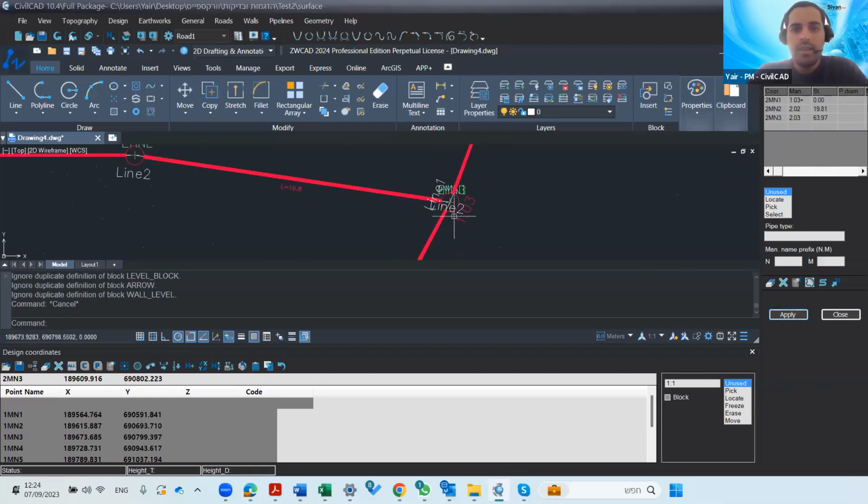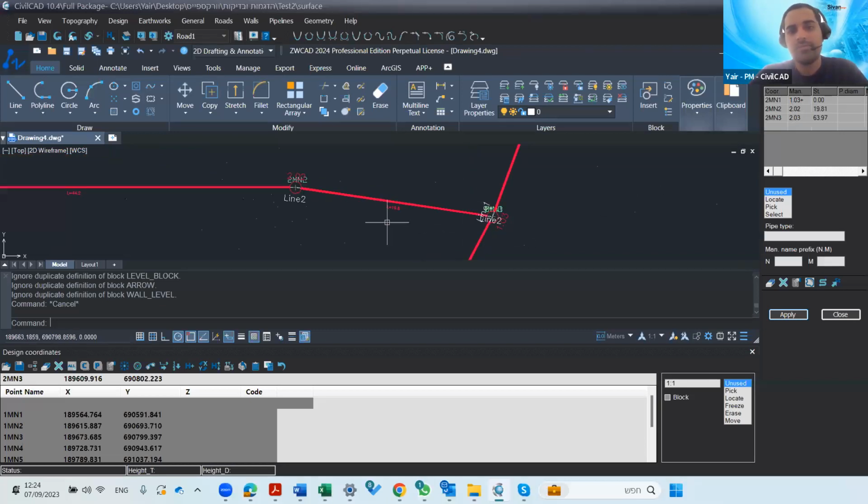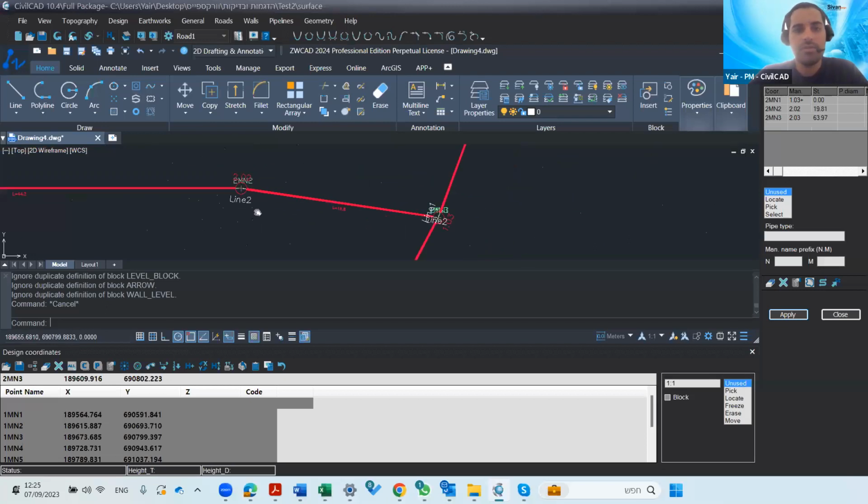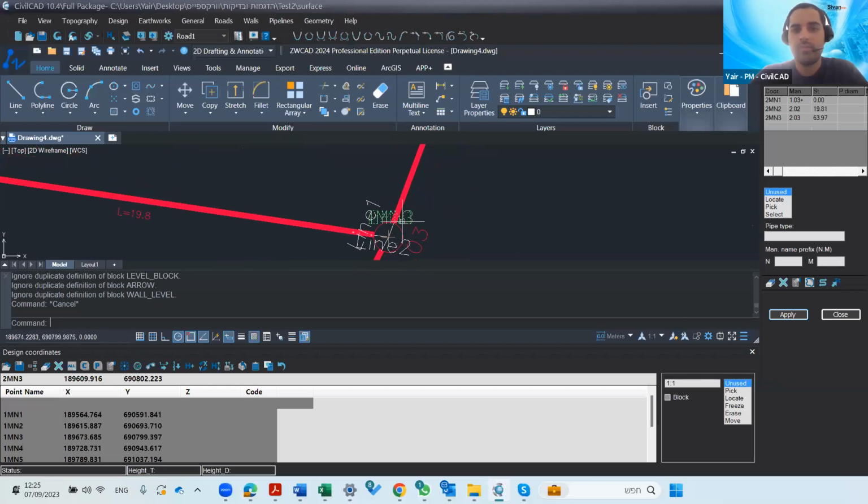Okay. Now you can see here 1.03 plus, which means that this manhole is shared with the main one. Okay, pipe number 1 is the main one, and this is the secondary one. I have the length of the pipe, and it is connected to manhole 3. Let's, for example, do it also here.